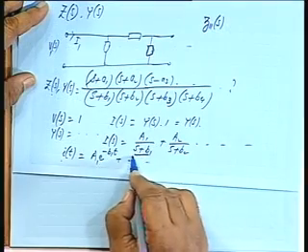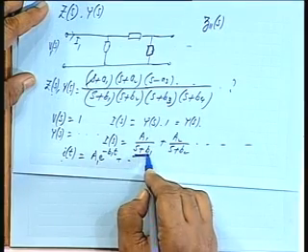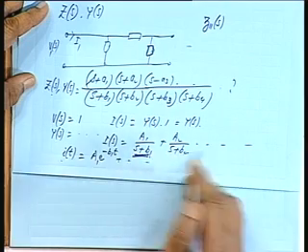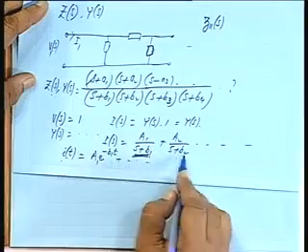It goes against the principle of conservation of energy, is it not? So, it cannot go up, it can only die down, all right. So, from the conservation of energy principle, the factors will be of this type, not (s - b1) or (s - b2). What does it mean? (s + b1) means the roots b1, b2 etc. should be in the left half plane, all right.